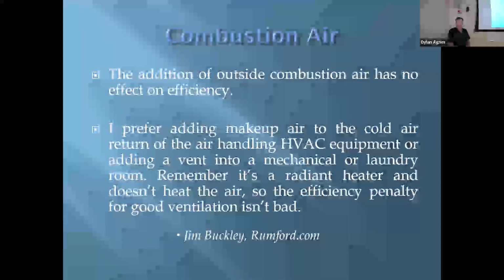You can do it one way or the other, but it doesn't make any difference. And so his opinion was adding makeup air to the cold air return, which is something that I've supported for a long, long time. And what he's saying, and the reason I quoted him, is: remember, it's radiant heat. We're not trying to heat air. So the efficiency penalty for good ventilation isn't a bad thing. He's saying, if we need more air in the house, let's bring more air in the house. You're going to get better ventilation, and it doesn't necessarily come with a big penalty. And my testing says the same thing.